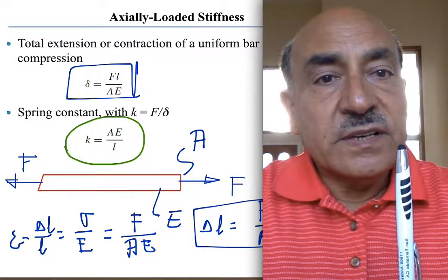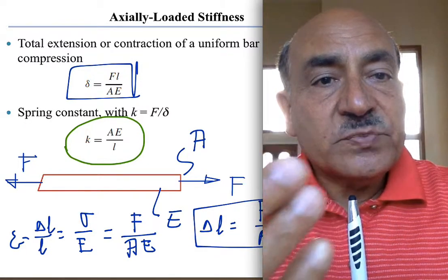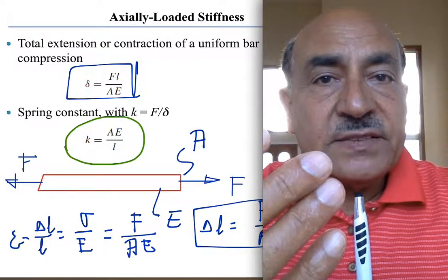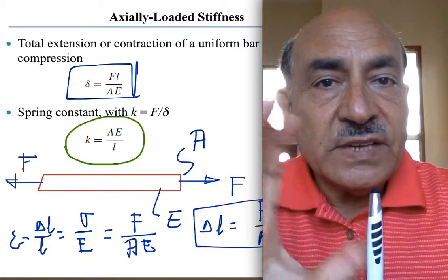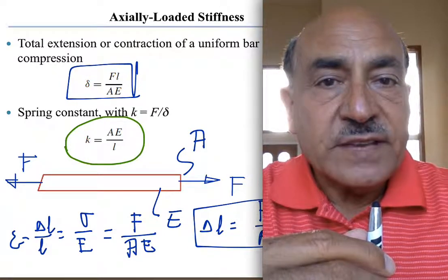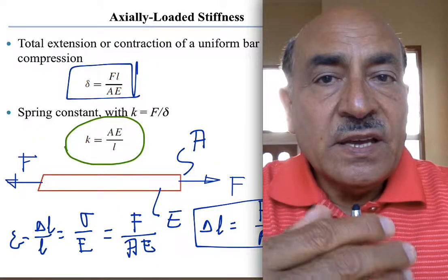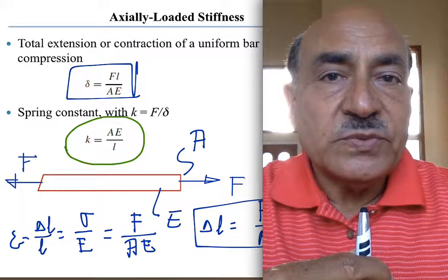The torque will induce an angle of twist. If the angle of twist is proportional to the torque, we will consider this also as a torsional spring, because if we release, then we get a force that can lead to an oscillation, for example. So we could use this as a torsional spring. That's another type of spring that we would consider.